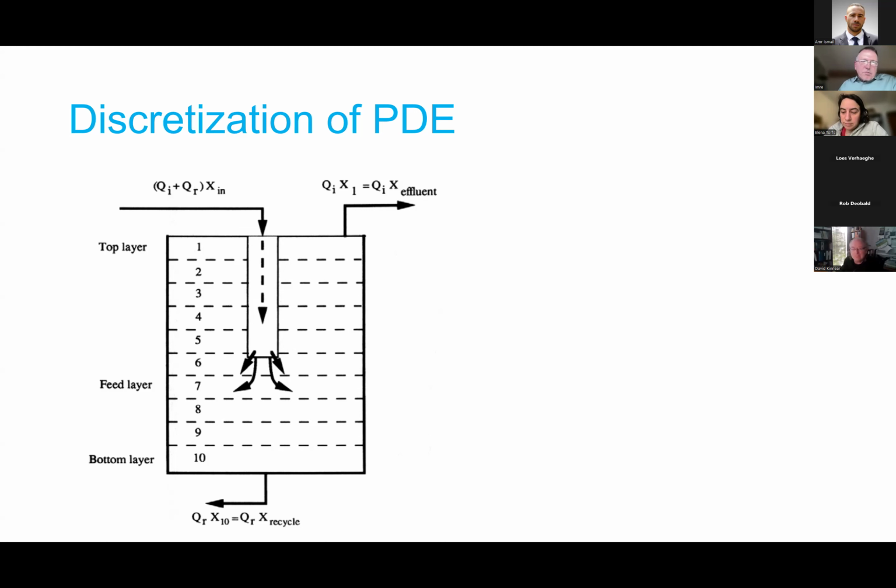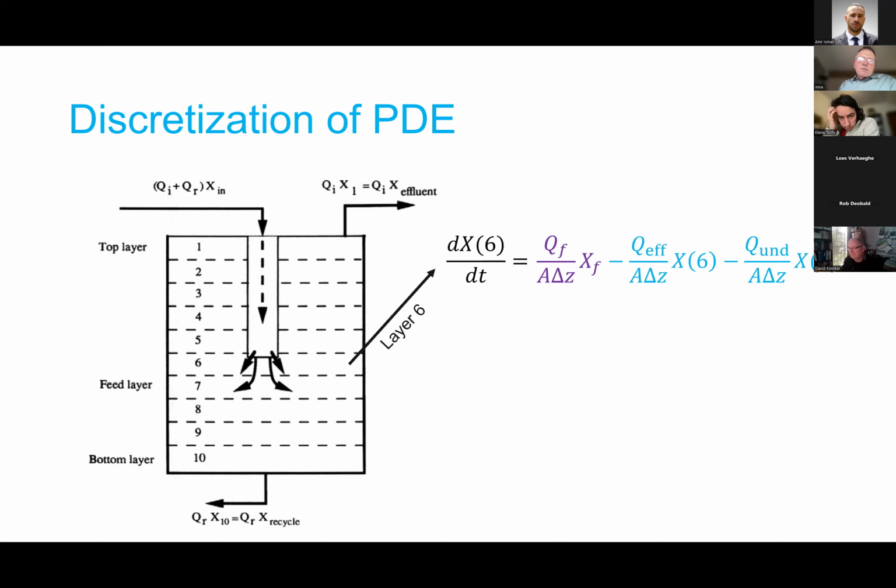The other thing I wanted to point out is that we have layer 6 here, and the input, the MLSS, is coming in, and then it splits immediately. You had one slide which was even better than this, which splits immediately up and down for flow up and down. What that would mean is that this model doesn't wash solids out until the blanket gets into the feed layer. So for that, we developed another empirical method: depending on the flow, the surface hydraulic loading, we can reduce this feed layer. So it gets deeper and deeper when you increase the flow, and then it will push solids up. I know it's not very scientific, but that's what's being used in the commercial packages.